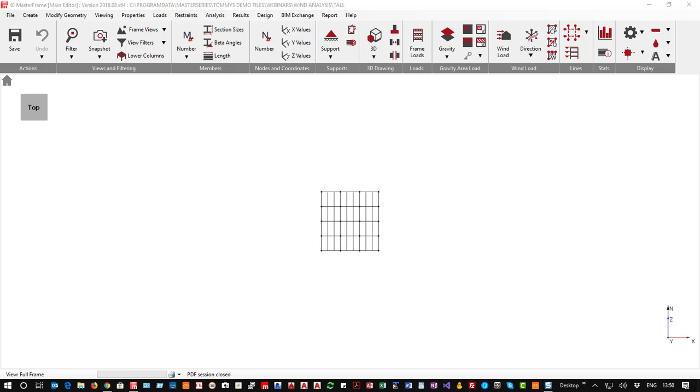Can you get the wind panels to model without a ridge member? Yes, you don't need to add in a physical member. You just add in a dummy member. In reality, the purlins are going to do some structural good on transferring load from one end to the other.